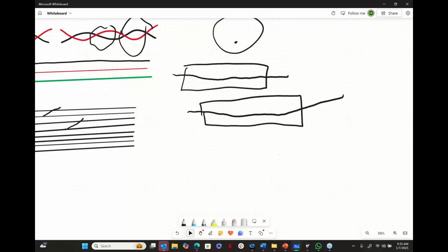And at some point, that cable is going to get too close to possibly a motor or a light bulb or something. So when I'm teaching them to use a TDR for the first time, I let them know, I see the problem right here at 22.5 feet. They pull that cable out and they're like, I beg to differ with you, homie. There's nothing wrong with this cable. And I'm like, yes, it is. It's on the inside. Trust me. And don't call me homie.